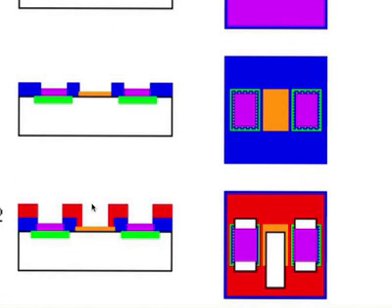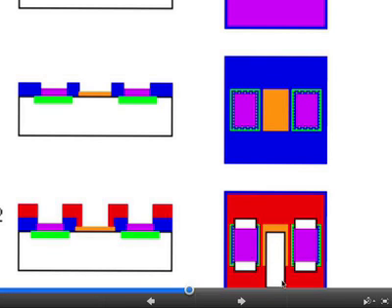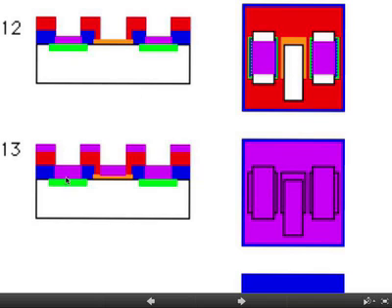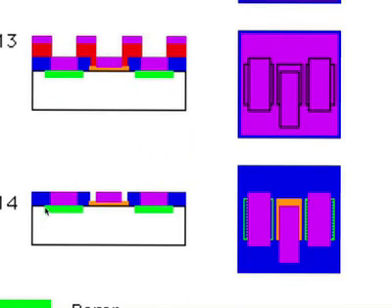So you put photoresist again. Just skip the step. You open up the gate oxide. But you can also open the source and the drain because you probably want enough metal to actually contact it out. So you open up the gate oxide, which kind of looks like that. It's a little bit shifted, so you can actually contact it from the side with metal. Later on, you will see that. Then you put down aluminum again. On the source and the drain, you just build up more aluminum. On the gate, you build up aluminum on top of the gate oxide. Then you remove the photoresist, and you pretty much have your device.